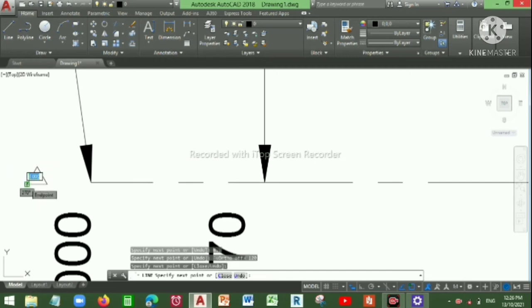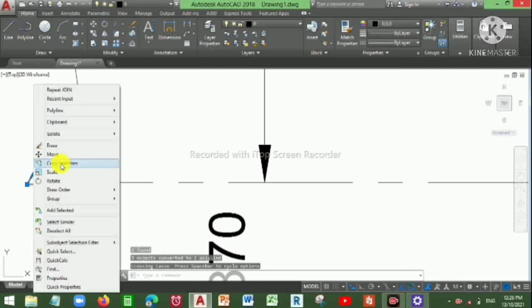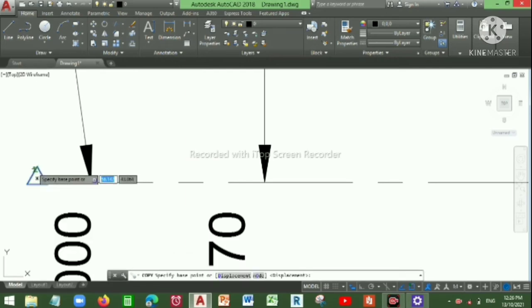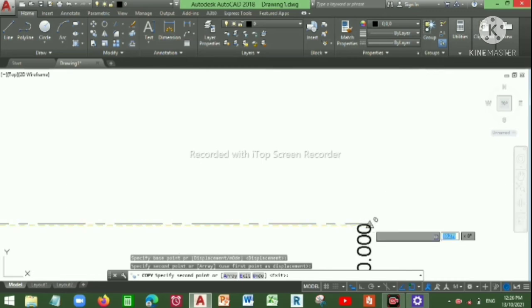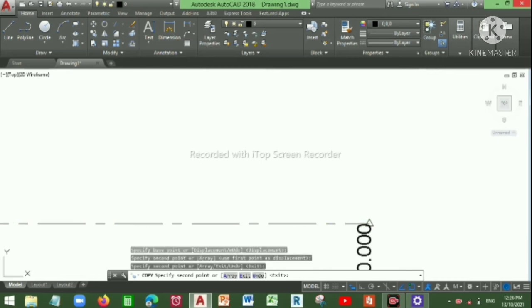Yes, after clicking on a triangle, select your triangle, click on join, press enter, click on your triangle, right click on copy selection, click on the center, move it right at the center of your endpoints. This is just for reference, you might have to change the dimensions of the triangles according to your needs.